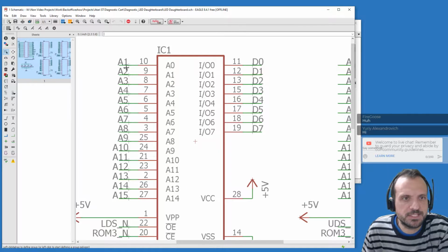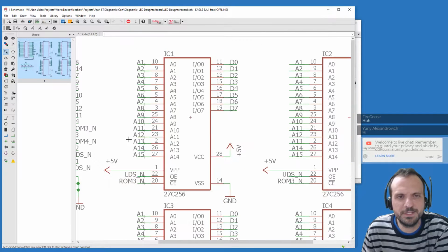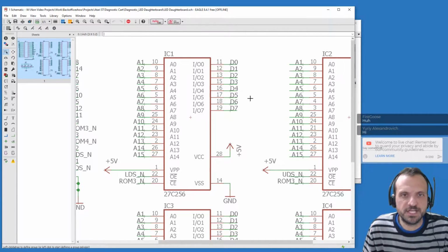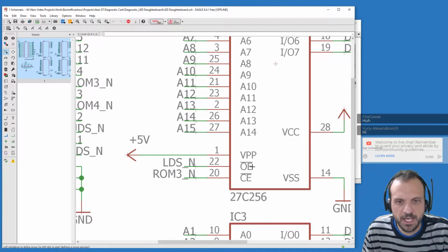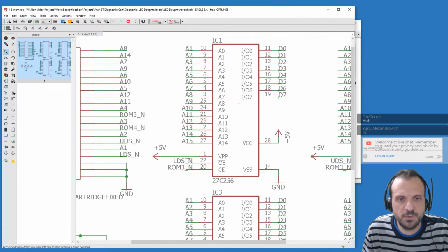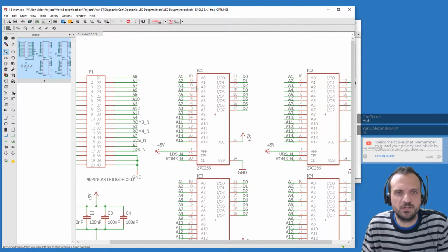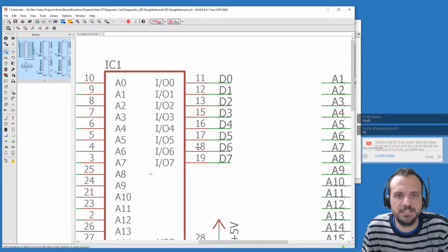So these are the address lines. You can see them here, address 1 to 15. Hang on, 1 to 15 is an interesting number, isn't it? It's not as many address lines as you'd normally hope for. But you can see here, A0 to A14, so it's not the 8 to 16-bit. And then you've got your byte of data out coming here, and your output enable, and your chip enables on those. So for most cases when there's data traveling along the bus, you'll be able to get the address LEDs going nuts, and the data lines going nuts.